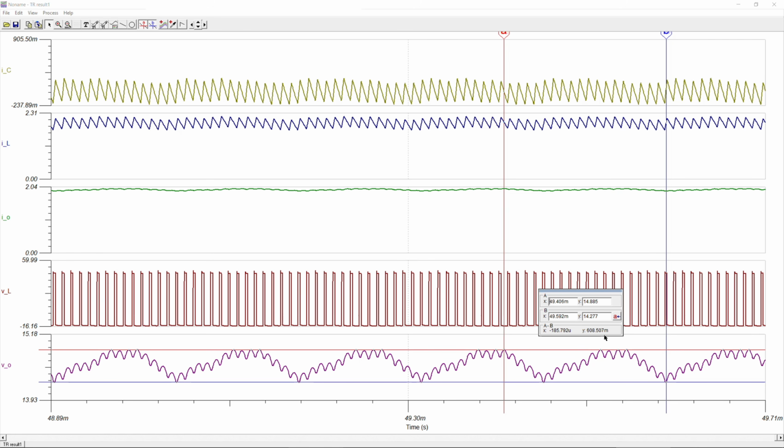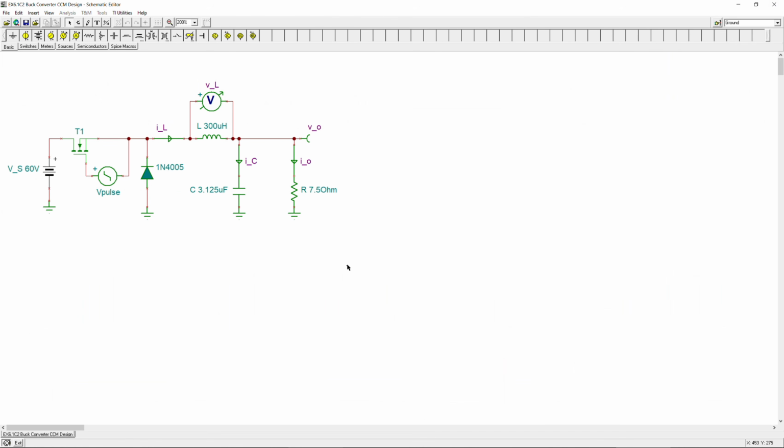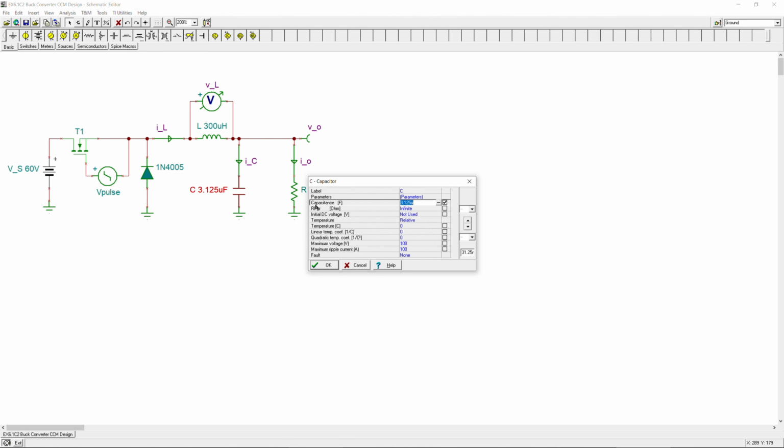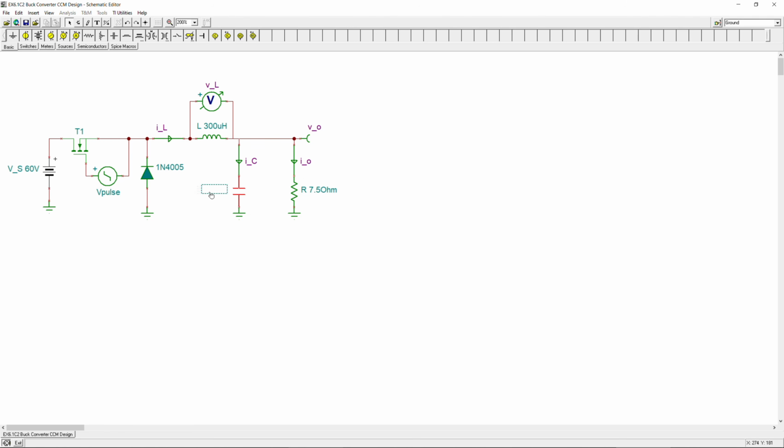So we need to adjust this, improve this to get lower than this value. Okay, so let's increase the capacitor. We have seen that 20 microfarads will do the job. So we'll increase that to 20 microfarads. Why do we increase? Because the larger the capacitor, the lower the output voltage peak. That's what we do. This is the reason for tuning. You can say I will tune this one, but that will also have an effect on other parameters. So this is the part where you have more control over the output peak voltage. So we only change the capacitor.